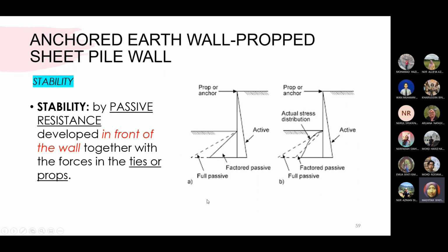So in terms of the stability, as I mentioned last time, when we analyse a retaining wall, whether prop or embedded wall, stability is something we cannot avoid. Just recall our last lecture on the gross pressure method, where a factor of safety of 2.0 is already inserted in the passive pressure diagram. So this is the requirement when you adopt the gross pressure method to analyze the retaining wall.